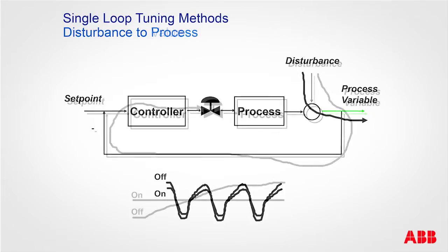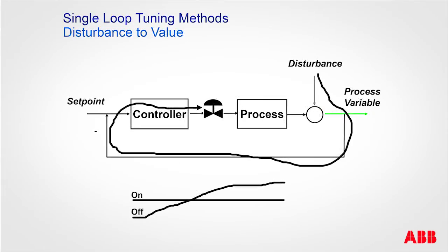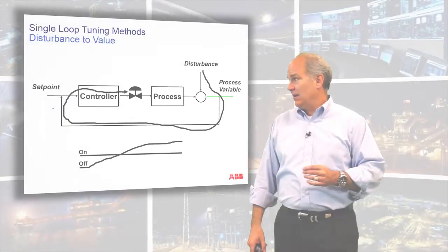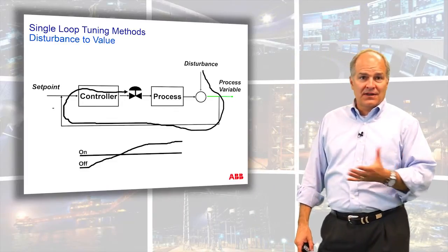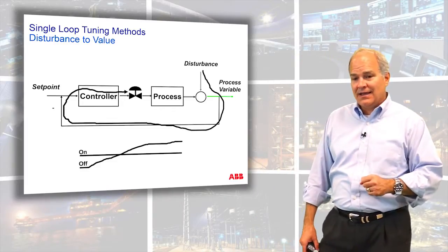So you can see what happens. In this case, if it's a low frequency disturbance, it's being passed and we actually have time in the feedback path to fix the problem with the actuator and compensate for it with the actuation device. And so it doesn't show up in the process. That's the feedback.